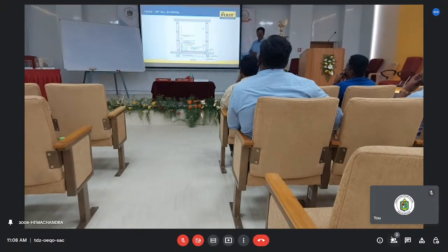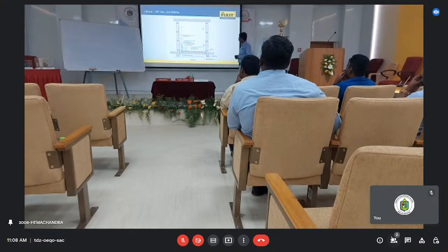That coating may not be possible for this type of structures, precast structures, board structures. So the system should be good enough to take care of the elongation. So we give our R-type. R-type has more than 350% elongation. That will take care of the movement accommodation in the joints.